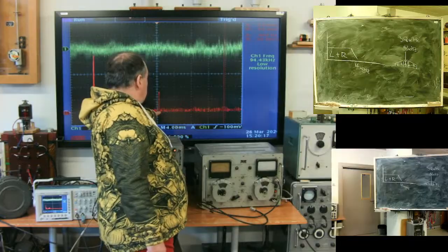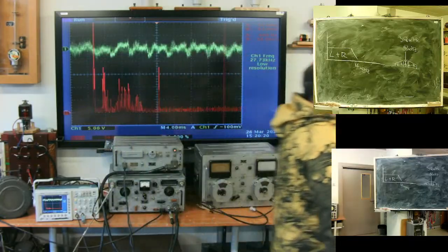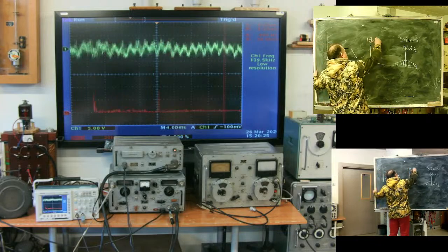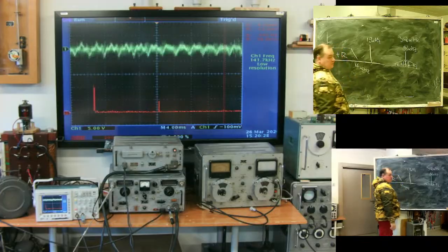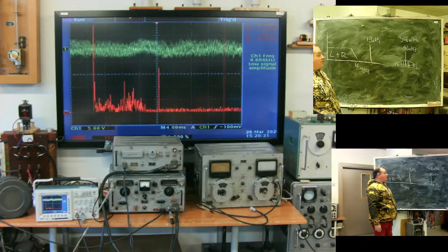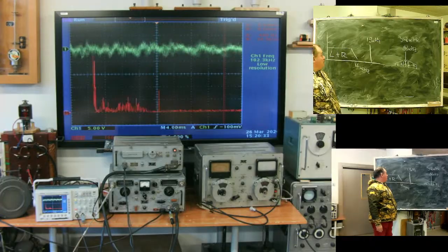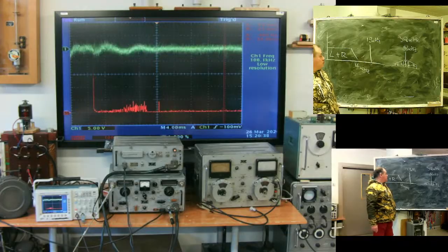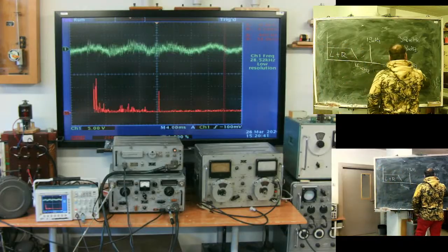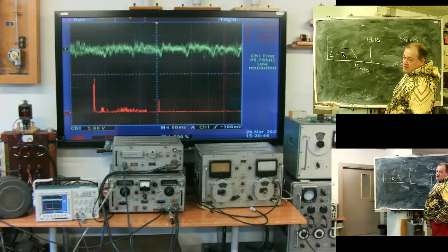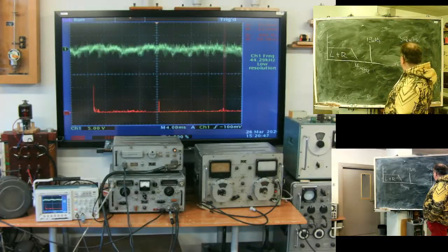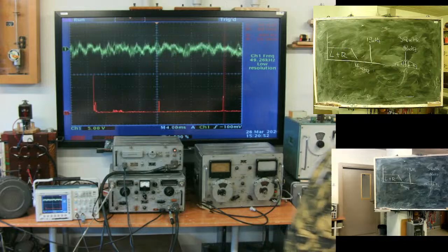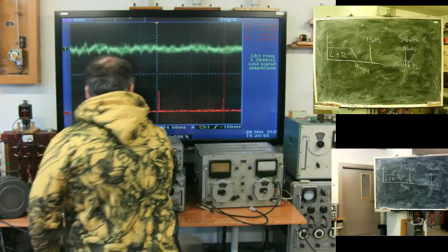Here at 19 kilohertz, above the hearing range of humans, the pilot tone is transferred. This pilot tone is used to synchronize a local oscillator to recreate the 38 kilohertz necessary to demodulate the L minus R signal.